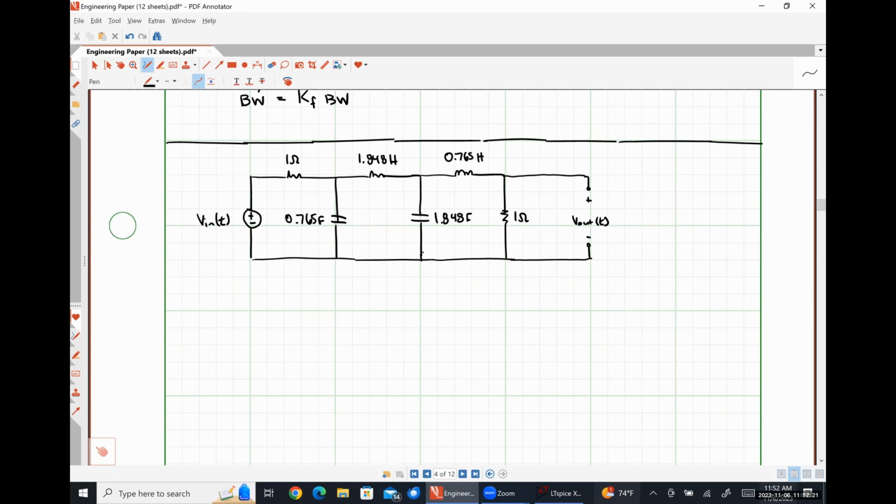Now, this particular Butterworth filter is what's called a normalized Butterworth filter, in as much as it is designed specifically to have a cutoff frequency of 1 radian per second based on a 1 ohm load impedance and a matched 1 ohm series source impedance. Okay, so this is literally straight from the table that you guys will be getting before class on Wednesday for designing these filters.